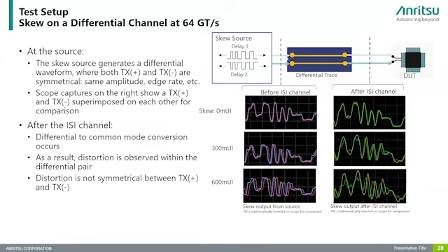Again, you can see the input of the trace and the output of the trace. Now, 0 milli skew is completely matched. To see the skew visually and clearly, the scope has a function to invert the positive signal. So now you can see them completely overlapped.